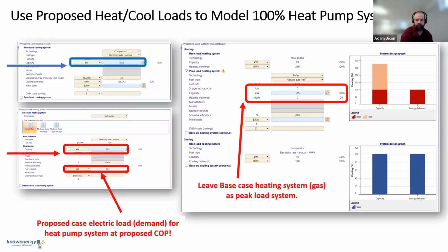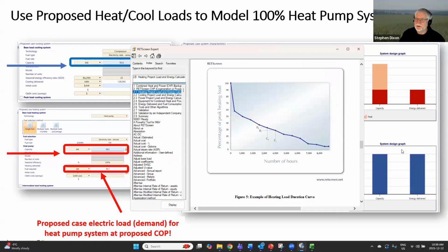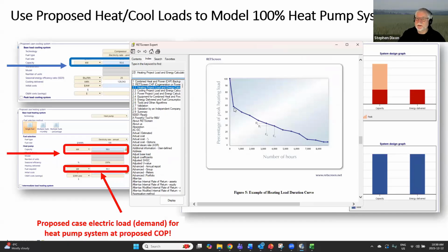Yeah. So when I build this hybrid system later on, I'm going to use a number like 70%. I'm going to drop it down, or maybe 65%. So what I'm really going to end up doing is just chopping that off and sizing the system much lower to still meet 98% of my energy. But I'm not meeting anywhere near 100% of the full demand. It's those few hours a year we're going to let the gas do the job and take a little bit of a hit on carbon. So yeah, good point.